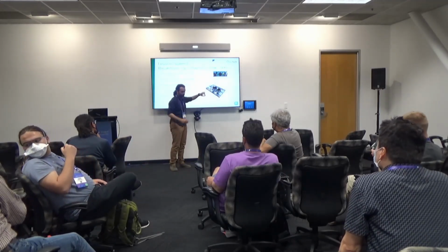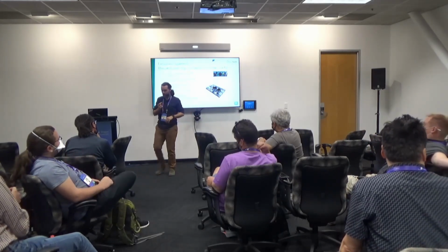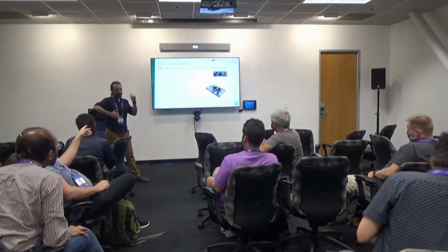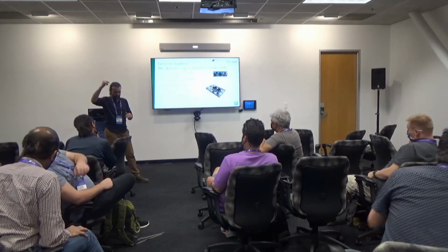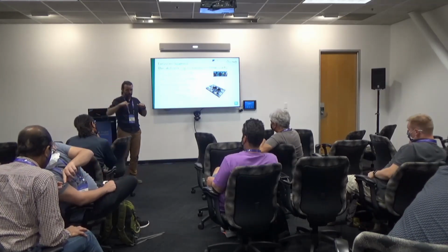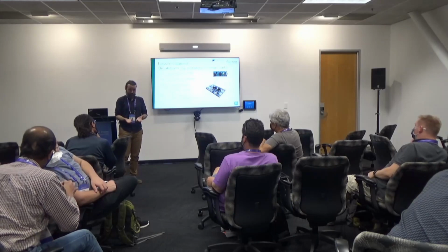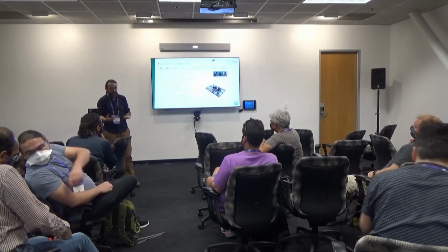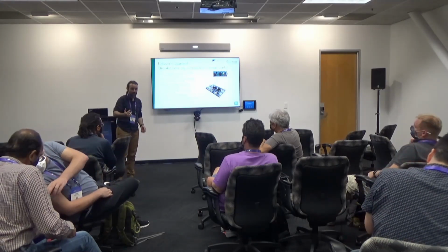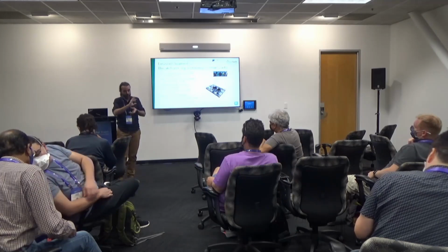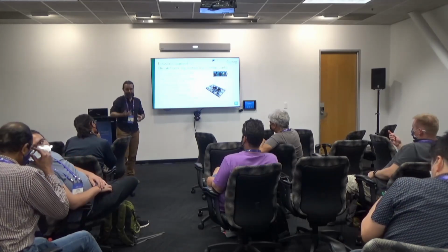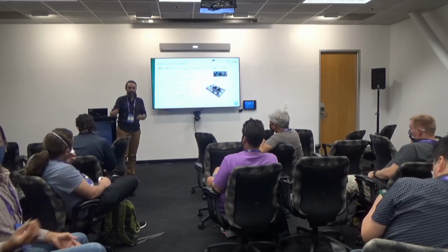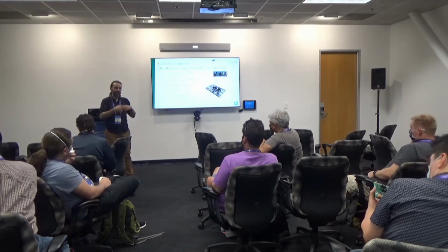developed a small power converter that feeds the whole board. And that power converter can go from 10 volts to 110 volts on the input. So when we power up the high side, it powers the board, so it powers the microcontroller, and the microcontroller starts. So this is on the power side. And if you feed from the low side, because of the way the topology is, there's only a diode that goes in the other way. So the power gets to the high side, so it powers up. So either way, whether you connect your source on the low or on the high side, it powers up the board.